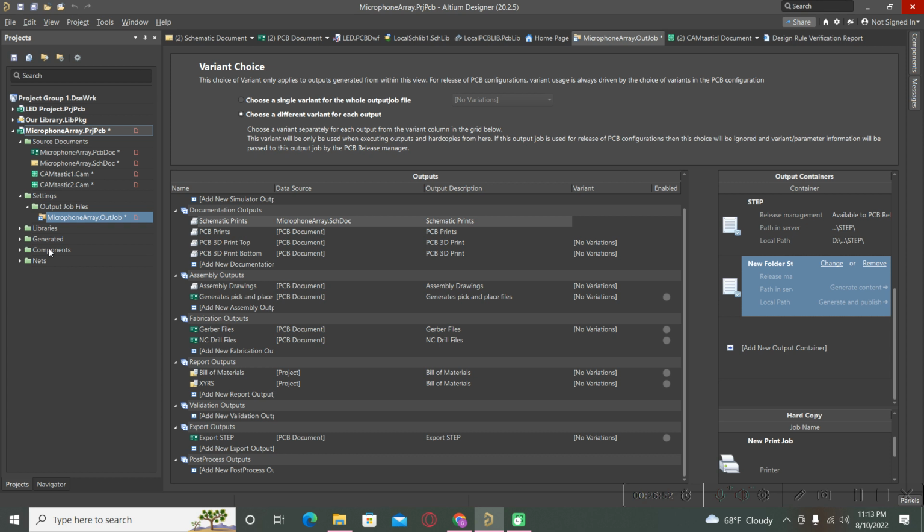You can simply generate your Gerber and your files, and you can give them this file to give you a price quotation for this. And after that, you can generate all the other files, the bill of materials, and you can order the components and build your first board prototype.